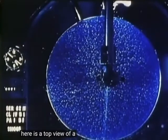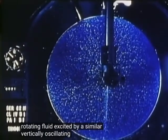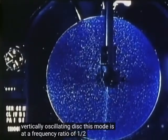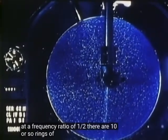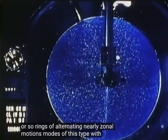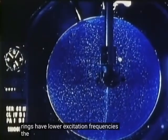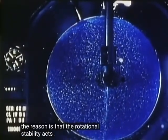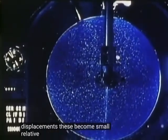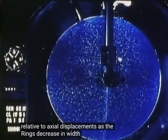Here is a top view of a larger body of rotating fluid, excited by a similar vertically oscillating disk. This mode is at a frequency ratio of 1/2. There are 10 or so rings of alternating, nearly zonal motions. Modes of this type with more rings have lower excitation frequencies. The reason is that the rotational stability acts mainly against radial displacements, and these become small relative to axial displacements as the rings decrease in width.